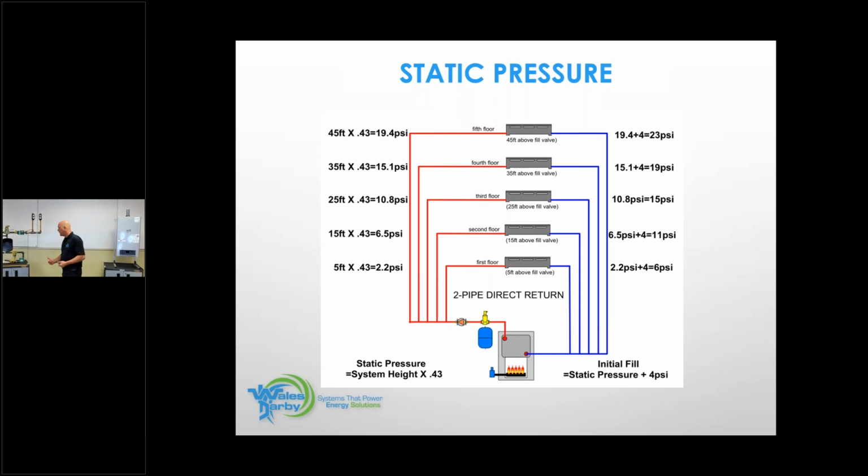It shouldn't. What I get nervous about is I see these just hanging out here on its side, but they're not supported. So I get nervous about it from that standpoint. From an operational standpoint, it should not matter because at 12 PSI, both sides are full. Normally, though, this is a small one. If I see a 60 or a 30 on its side and it's only being supported by this fitting, I'm not so comfortable because if the diaphragm were to fail and I fill this with water, it's going to be a tremendous amount of weight there. That would be the only downside.